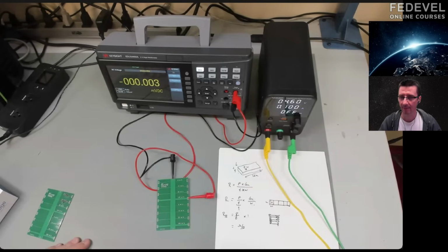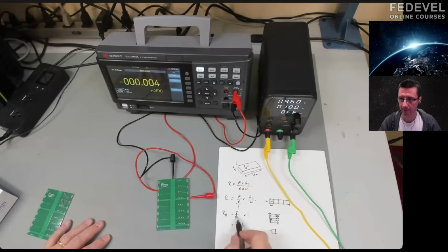Well, the crazy thing is, and I think it's counterintuitive. If I have a square that is 10 mils on a side, and I measure the resistance from one edge to the other edge, and so let's put in the numbers here so we know what that number is. For bulk resistivity of copper and the thickness for 1 ounce copper, I'll just tell you the number, 0.5 milliohms per square for 1 ounce copper.